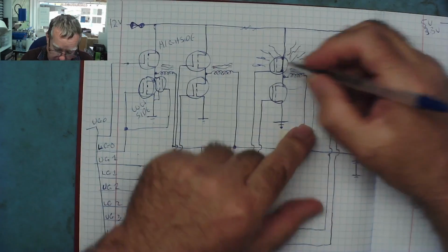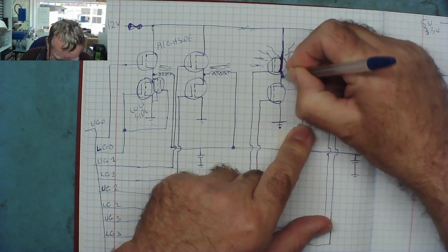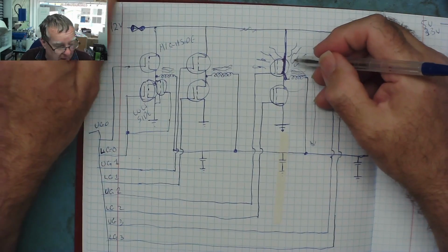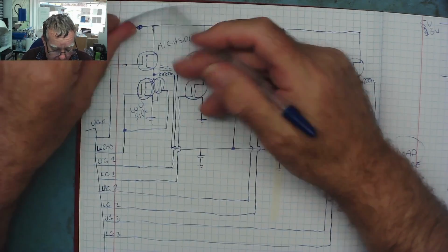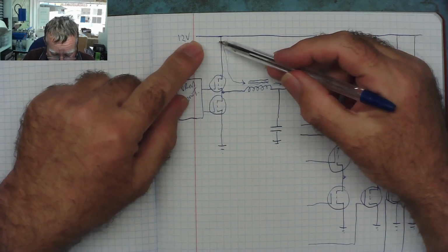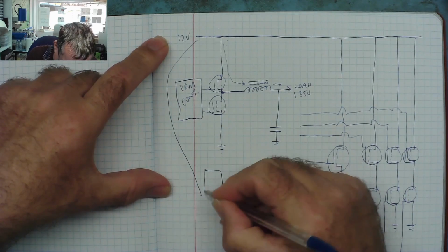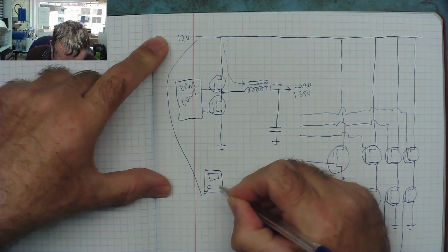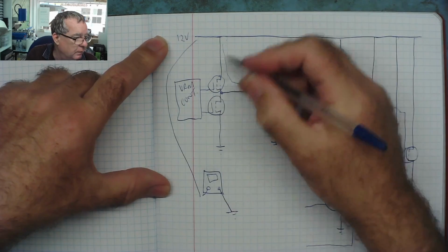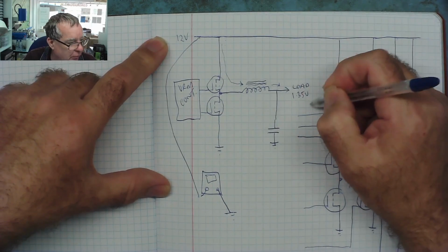And this is where your shorts are. So you now know the short is here into this coil: short circuit high side MOSFET. This is why when we measure from the 12 volts, and I'll just refer back to the previous diagram, the resistance from here, here's your test meter. I always draw an analog meter. It could be a digital meter. When you measure to ground from the 12 volts, the resistance you see is the resistance of this load.